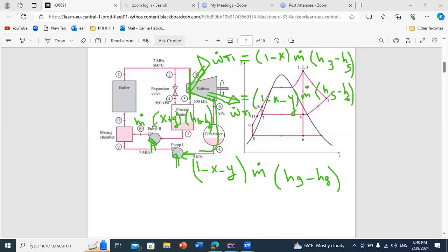And then to calculate Q dot process, we already did it together. You just have to know what are x and y. You calculate Q dot process as we did. And just now for our boiler, it's m dot times (h1 minus h11). Just to get h11,